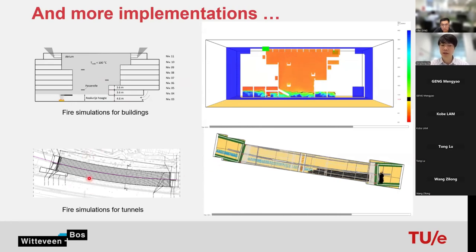And here we had more tunnels in Antwerp, and I checked when a truck fire occurs, will these ventilators have the capability to blow all the smoke to the front of the traffic, so it will not have any back-layering, so people can escape safely.